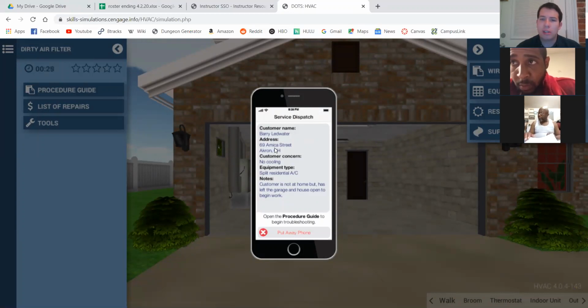Is it next to some dog houses? I had a unit that was 1 year old, and just because the units were next to a pair of dog houses with big fluffy golden retrievers in them, I'm not kidding you, I didn't have to do any cleaning. I could just pinch and pull off a 1/4 inch thick layer of dog hair built up on that coil over a year. That's all it took, 1 year of operation, and their system was already failing. It was really, really bad to see. I had to go tell them, hey, you just got to get the dogs away from the systems. They just didn't want to hear that, so that was fun.